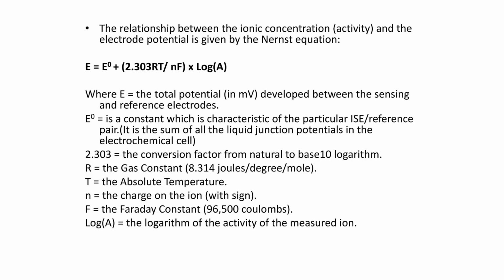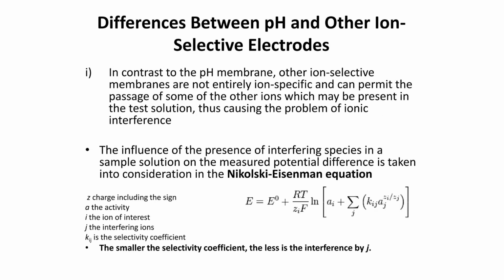And the most essential structural component of the pH electrode is the sensitive glass membrane. This membrane is uniquely used for permitting the hydrogen ions while blocking all other competing ionic species.